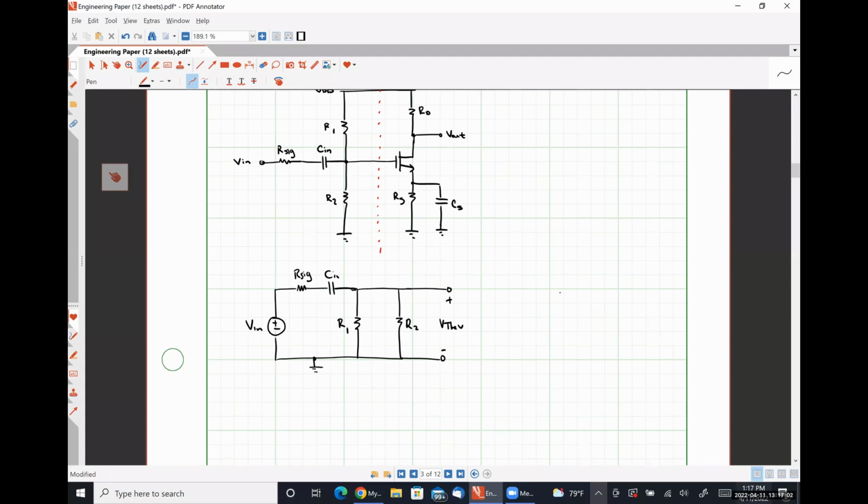So we have an impedance here that is R sig in series with the impedance of SCN. So that's an impedance, let's call it Z1. This is an impedance Z2. So it's just Vn times Z2 over Z1 plus Z2. This is a voltage divider. Wonderful job. I'm glad somebody recognized it.